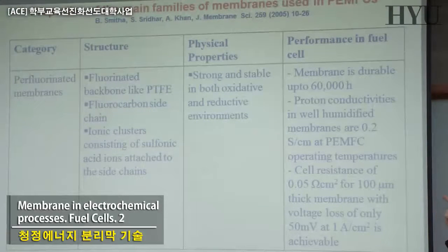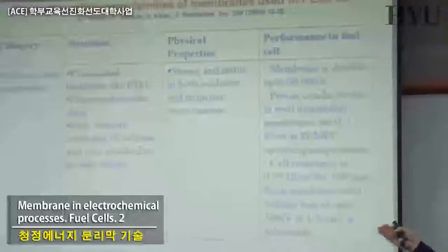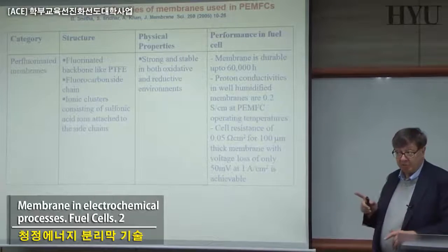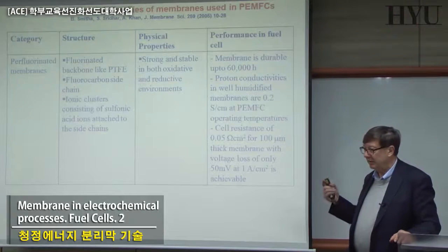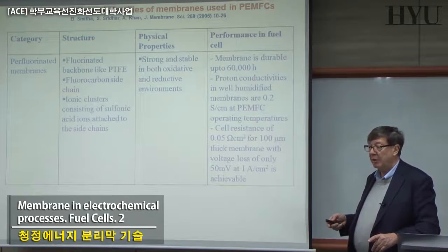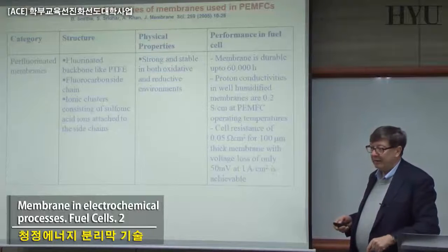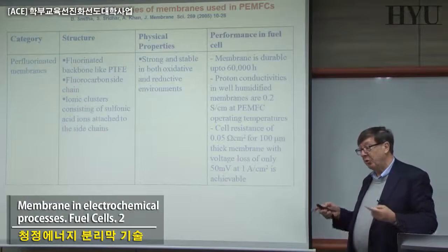Using fluorinated polymers, and also today non-fluorinated ones. The polymers are fluorinated not because we need fluorine, but because the chemical stability and the transport numbers for different species are quite interesting. If you can do the same with a non-fluorinated polymer, which normally means a cheaper polymer, that can be a success. Today there are people, also in this department and in different places, including ours, working on non-fluorinated polymers. For example, polyether ether ketone, which we will discuss here, is a typical polymer where you can have interesting performance. You make sulfonation of these polymers.